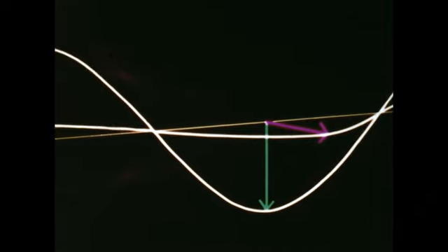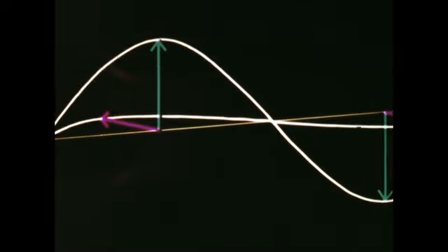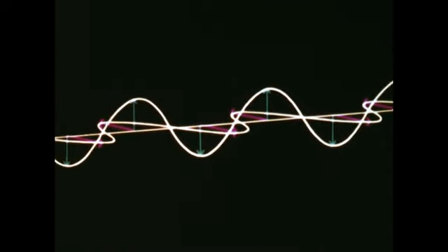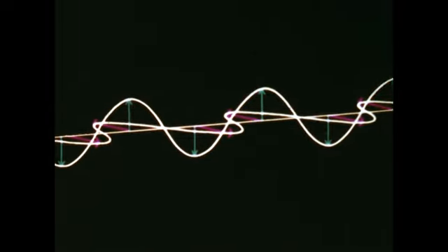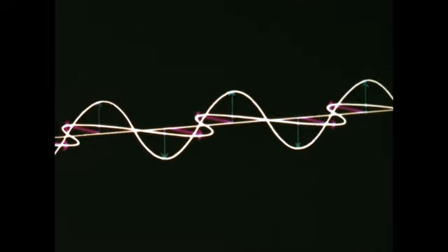The traveling waves are therefore said to be in time phase and space quadrature. The polarity of an antenna is determined by the plane of the E field. To obtain a maximum signal, both the transmitting and receiving antennas must be in the plane of the E field.